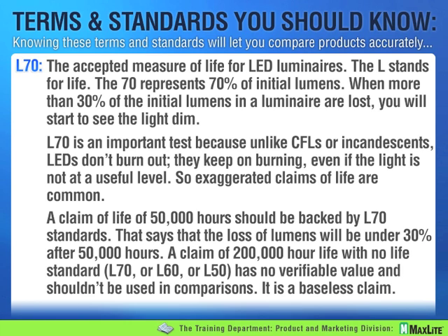So a CFL, you burn 100 of them. When the 51st one fails, you round off those hours. It's an 8, it's a 10, it's a 12,000 hour bulb. Same for incandescent, HID, so on and so forth. The other half of the world, they burn 100 lamps. This is basically an Asian spec, Japanese spec. They read and record the total collective lumen output of that 100 lamp array. When that depreciates to 50% is how they rate the life, which I think is a more accurate way, frankly speaking,